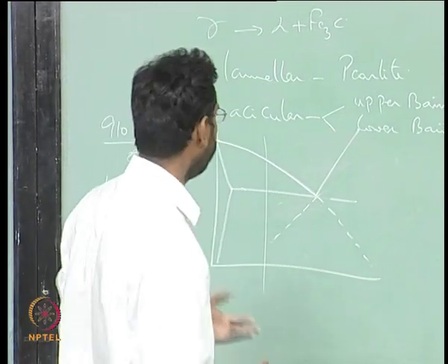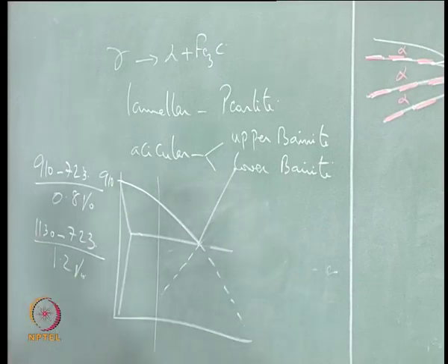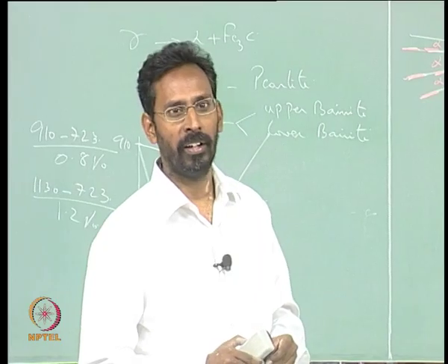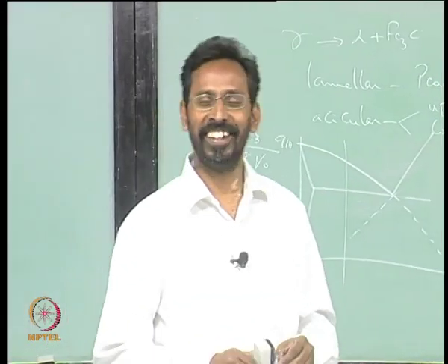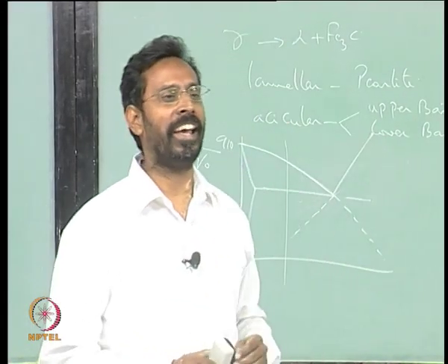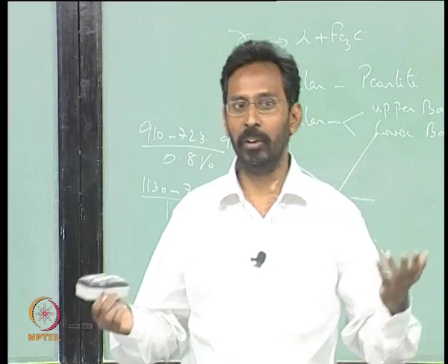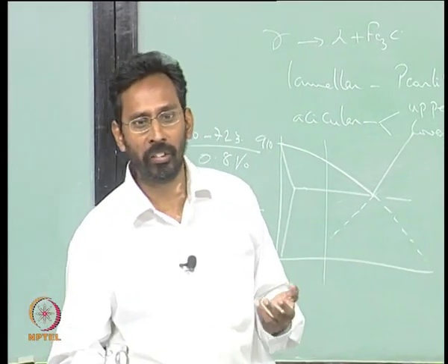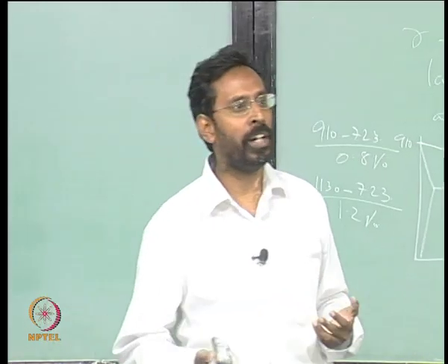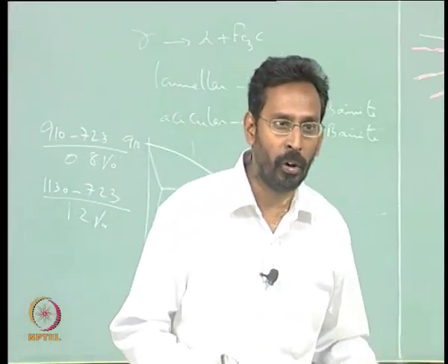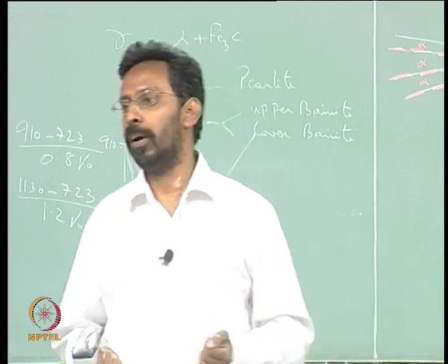Coring, why are you talking of coring? Why coring will be decreased, you are talking about. Okay, let us not bother, we are talking about heat treatment, in terms of the microstructures, coarser grains. So toughness will be better, coarser grains, hardenability is higher, you will get a higher hardenability if I take it to a higher temperature, because the grains are coarser, the number of nucleating sites for pearlite to form are lower,